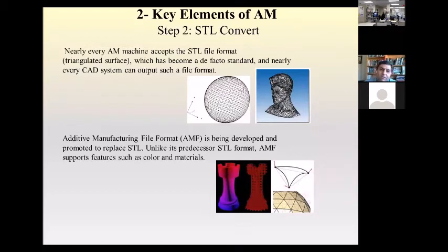So after you have your CAD file, through reverse engineering or drawing it, you are going to convert it to STL. As of now, STL is a de facto file standard that is triangular shape data, but you can make any geometry, and it is limited to only geometry. But more and more efforts are being made to add other features like color, texture, material, accuracy, standards, and units to that as well, because it's much needed and it needs to move with the latest technologies. As of now, it still is the very beginning file that was used for the first SLA process. It still is being used.